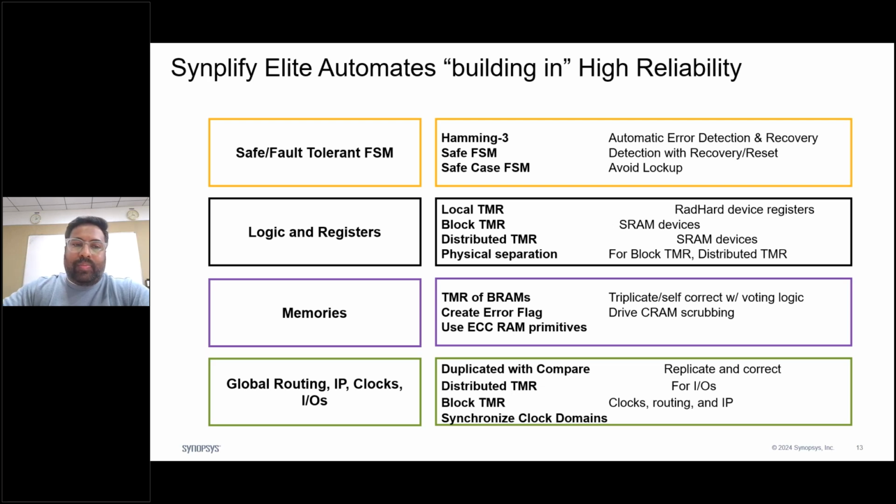Okay, to protect your logic and registers, it supports TMR. TMR is nothing but triple modular redundancy. What exactly happens in TMR is that it replicates your logic, and the copies are combined through voter logic. So if any single event upset happens, it will mitigate that, and your design is not affected.